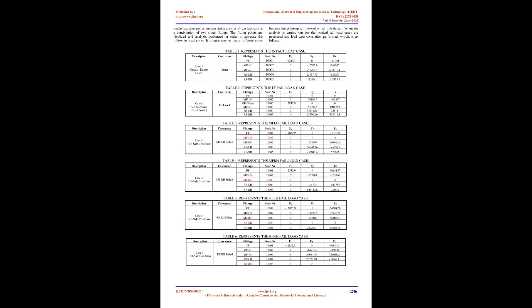The shear fitting is located at the leading edge of the root rib, followed by 2 bending fittings located in the middle and the trailing edge of the root rib. This arrangement is considered for the fact that a bending fitting is a combination of 2 shear fittings oriented in a different manner. Another main advantage of this configuration is that even if the front fitting, which is a shear fitting, fails, it will not lead to a catastrophic failure, as the 2 bending fittings will aid in taking up its load.